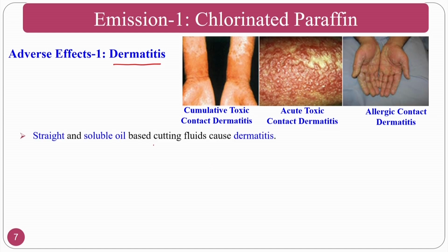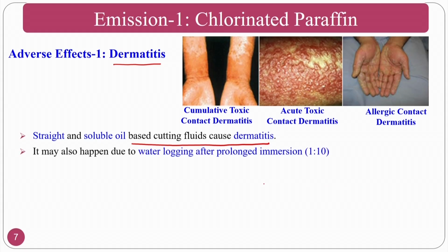Straight and solubilized cutting fluids cause dermatitis, and this also happens due to water logging after prolonged immersion. Normally, whenever you use cutting fluid, it is 1 liter of cutting fluid with respect to 10 liters of water. So, you have water in a major amount.